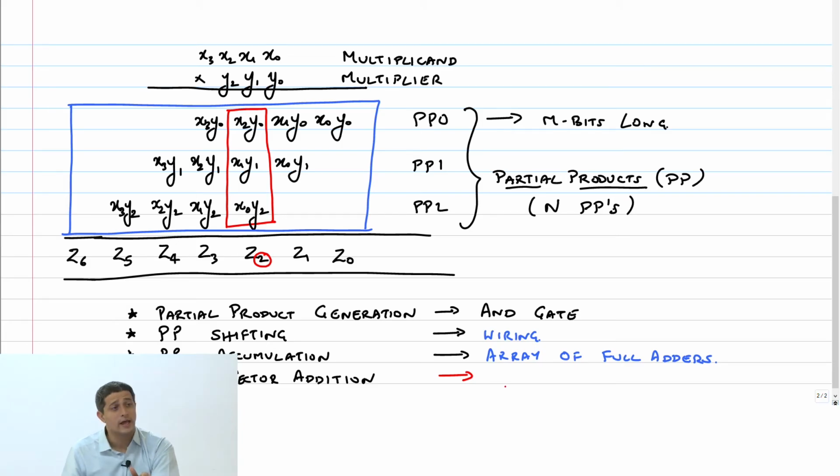And this is where the architecture of these other adders comes into the picture. This previous one, partial product accumulation, can be done using a typical ripple adder. Just a full adder, you ripple it through, do it nicely, you'll get it. Okay. But for this final vector addition, if you put a ripple adder, it will kill your delay.